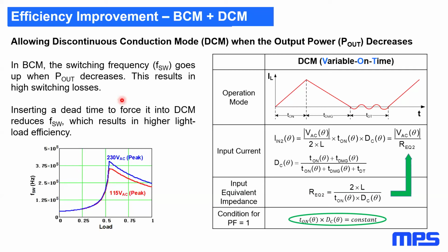So first of all, efficiency improvement. Again, I'm going back to the standards, because now more and more the standards not only ask for a given or a minimum level of power factor at full power, but also at different load scenarios, including quite light load conditions. And in most cases, these basic control methods are not doing very well at light load.